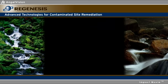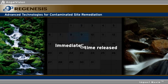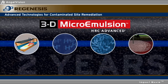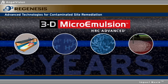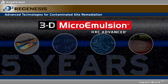Because our process provides for an immediate as well as time-release supply of hydrogen to fuel the demands of the anaerobic reductive dechlorination process, typical longevity for 3D microemulsion is up to 2 years or more on a single injection, and up to 5 years or more under optimal conditions.